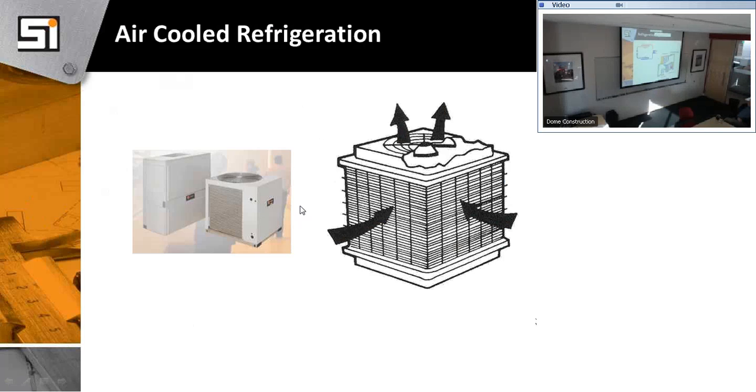So this is where you walk the roof. You've got the fan blowing heat out. This is the condensing unit. So at least when you're on the roof, you see what a condensing unit's about. This is a rejection of heat, so it could be a condenser or a condensing unit. The only difference is if the compressor is in it, it's a condensing unit. If it's just rejecting heat, it's a condenser. Again, you have it on the roof or maybe out the back side. So you see little split system Mitsubishis or something sitting out the side. That's where your condenser is, and probably your compressor.